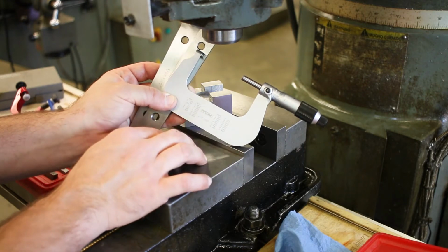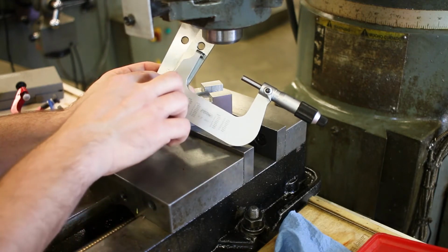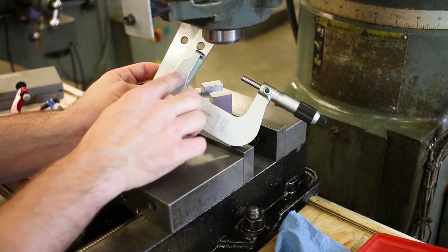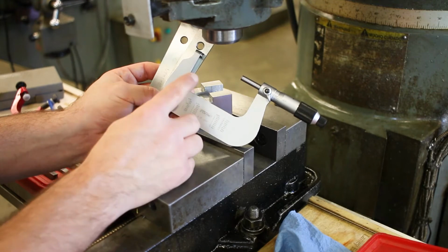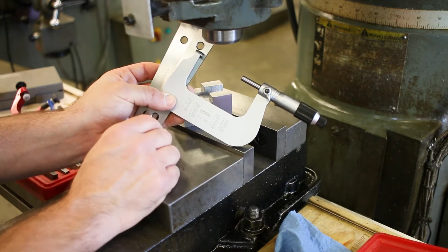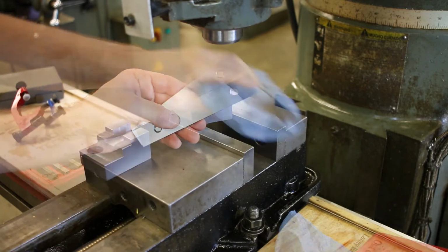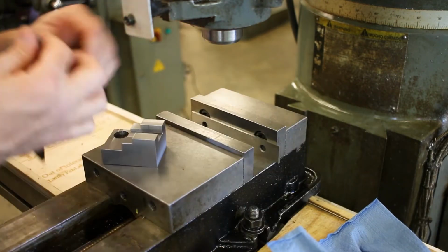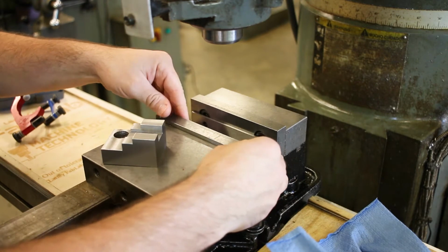And for this particular micrometer that I'm going to use, these 1-inch parallels are sort of the minimum size that we can use while still getting this thing underneath the part so that we can measure over those surfaces. So this is what I'm going to use. I clean everything up real nicely. Parallels get cleaned, just quickly wiped off with a hand.